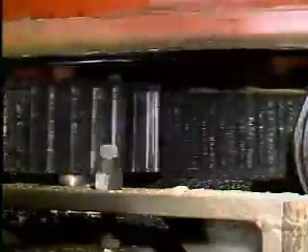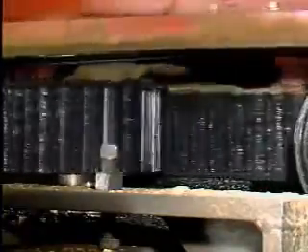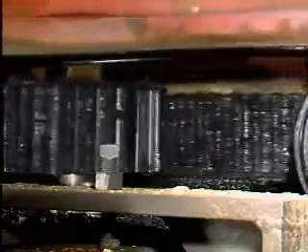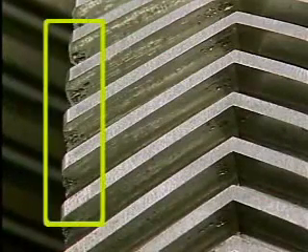Another lubricant condition that can cause gear problems occurs when lubricants become contaminated with dirt, sand, metal particles, sludge, or acids. Contaminated lubricants may cause a rapid erosion of gear teeth, which can cause teeth to break. The contaminant may also cause foaming of the lubricant, which can reduce the flow of lubricant to parts of the gear set, and this condition can reduce heat removal. You can prevent contamination from causing excess wear by replacing the lubricant at regular intervals.